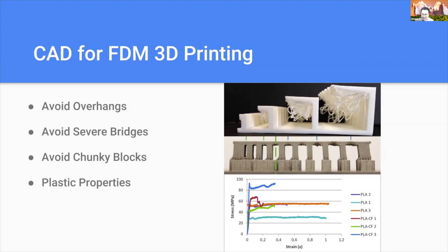There's different types of 3D printers, but in FDM, there's also different types of plastics you can use. The most popular ones are ABS and PLA. We use PLA in the MyHealth facility. Before you design something, you want to keep in mind the properties of the plastic, right? If you're considering a real world application, you want to see how the plastic can keep up with the daily stress and strains. If you're doing simulations, you want to make sure that the properties match or are scalable to what the real world application is later.